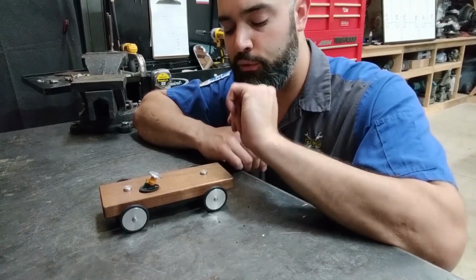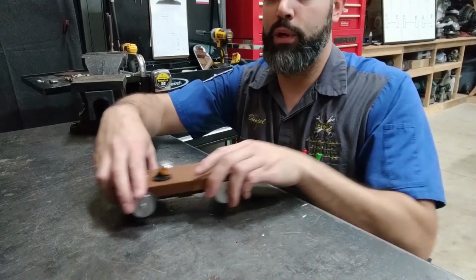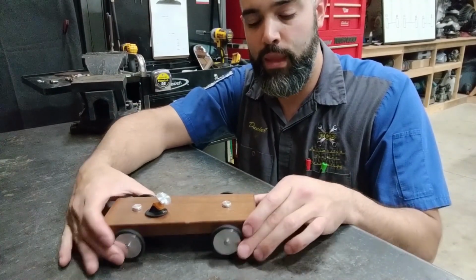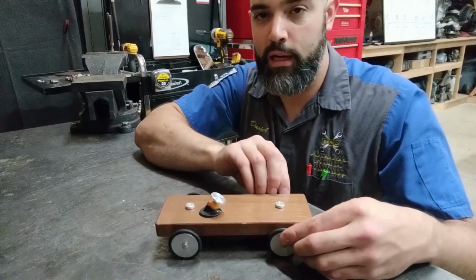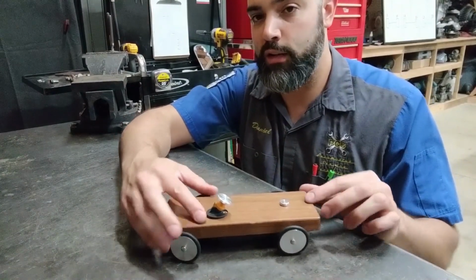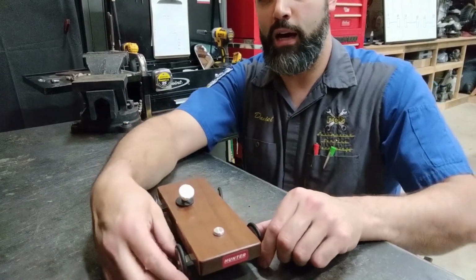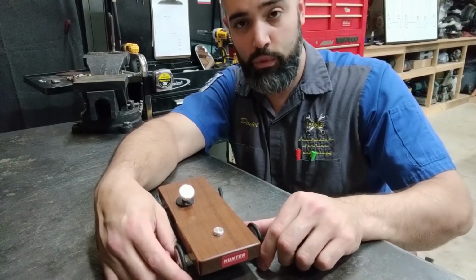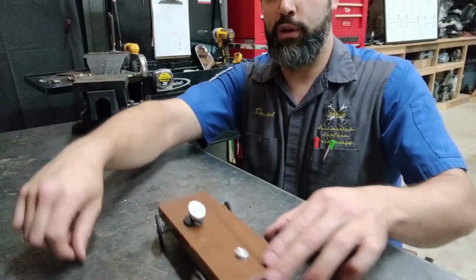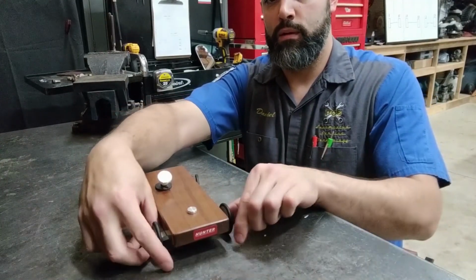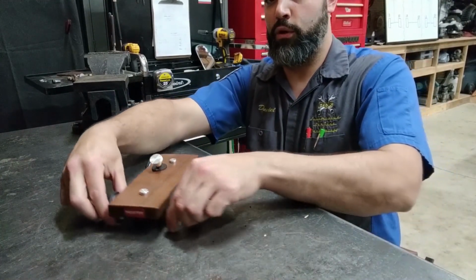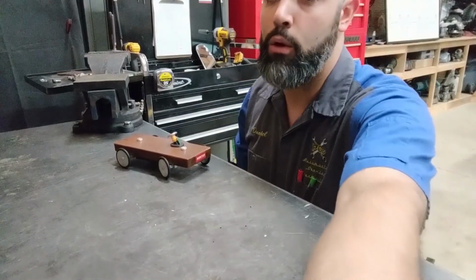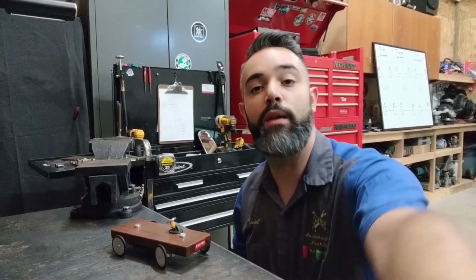So what happens if it happens on the rear wheels? If the rear wheels lock up and the vehicle is going straight, it will stop straight. If the rear tires lock up and the vehicle is making a turn or is on an uneven surface, the moment those brakes lock, those tires are going to continue going in the direction they were going when they broke traction. So during a turn, if they lock, they will continue going in that turn and the vehicle can spin around. In the worst case scenario, it can roll over or strike another person or vehicle or any other object.